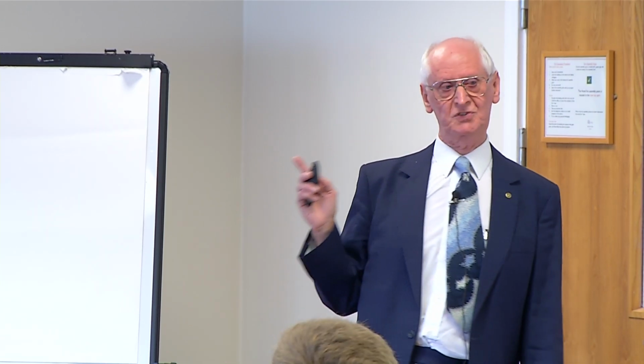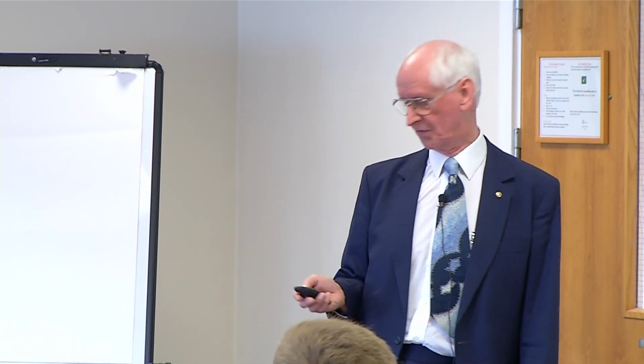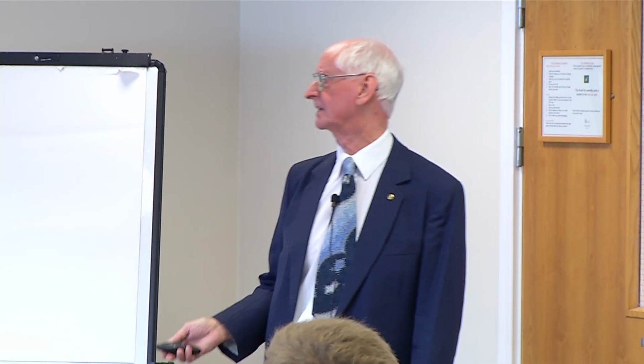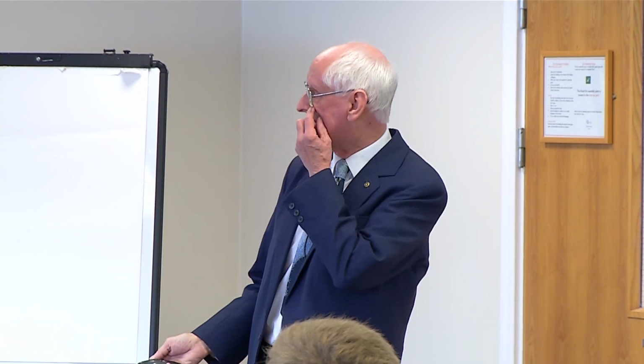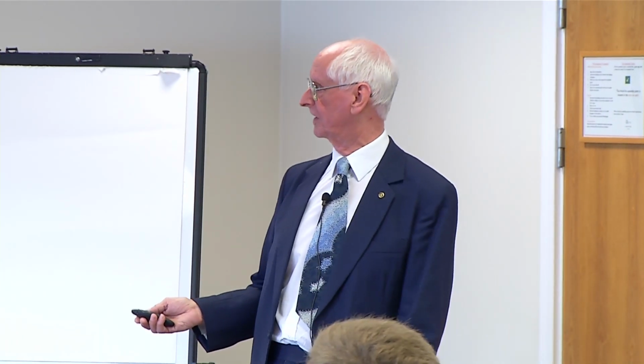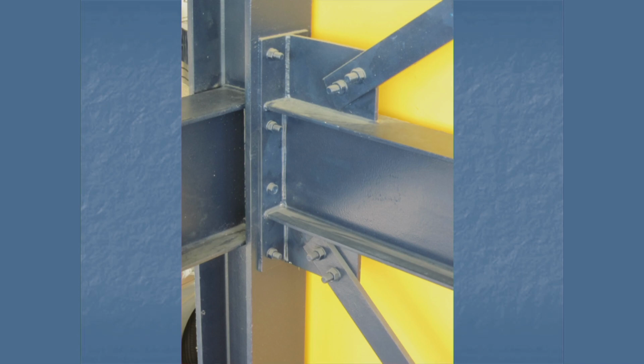If he didn't get the bolts right, what else have they not got right? Because this was done by a big contractor. And here you can see, this is another junction going up the stairwell. Again, we've got bolts that are too long, but notice that this one was put in the other way round to all of the rest.